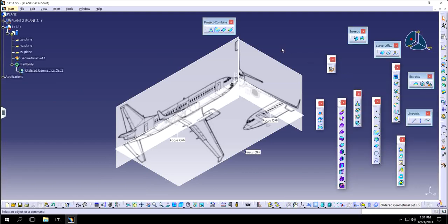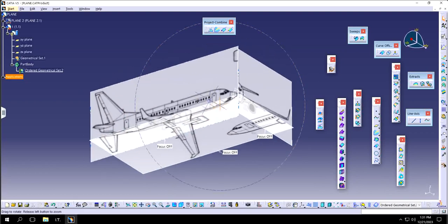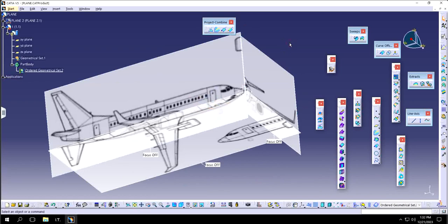First of all, you would need a guiding curve, as we already saw in the requirements. The condition for adaptive sweep is that we need a guiding curve that is right in the middle of the sketch. For example, it cannot be a guiding curve outside the profile. It needs to come right in the middle. Then we will make a sketch appropriate to the kind of shape a fuselage has. If it's circular, then we can use a cone, or even a semicircle or an elliptical shape.